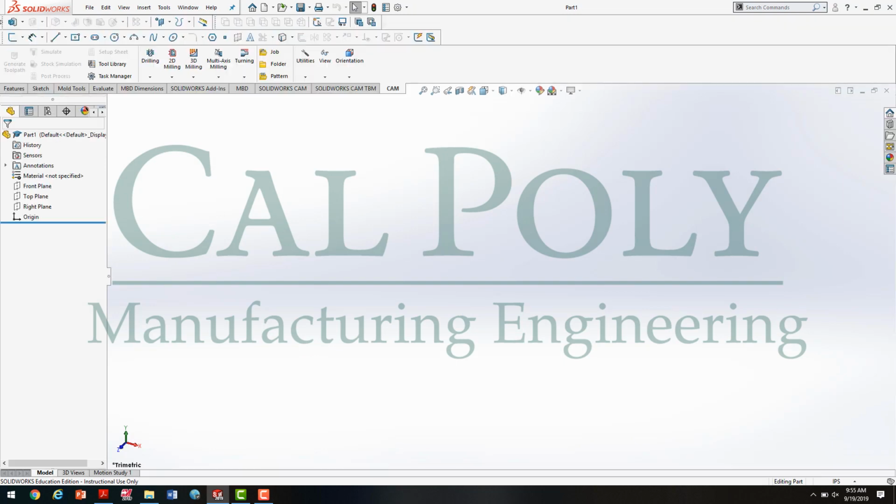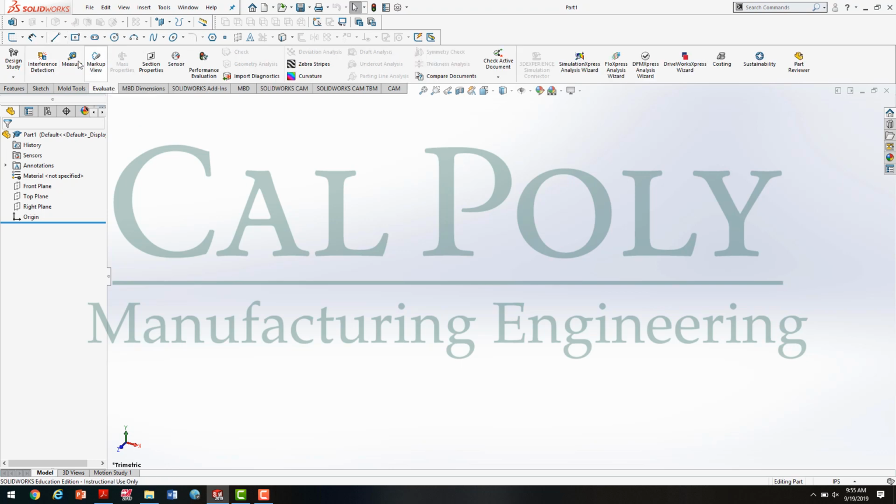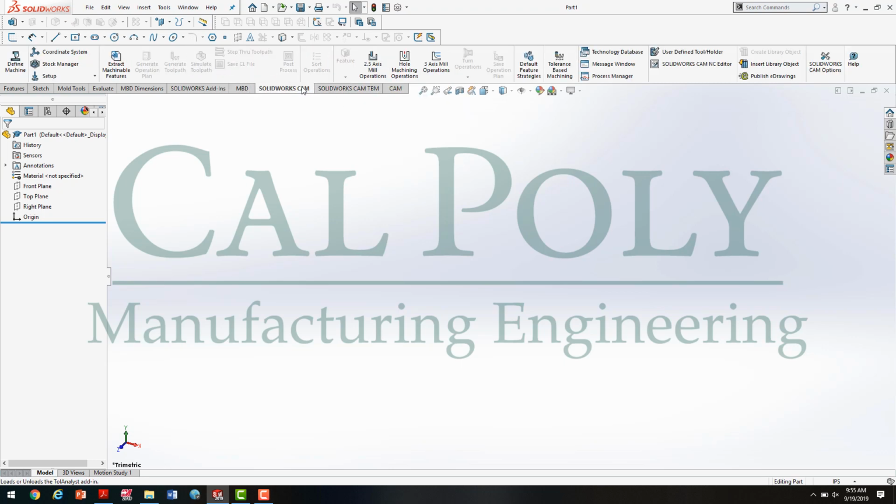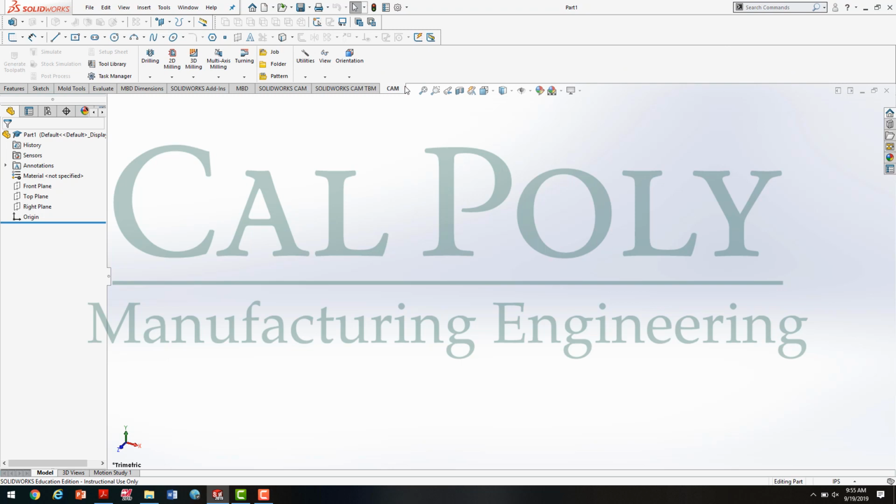Looking at the part environment, I have tabs. I have features, I have sketches, then I've got some advanced tools like mold tools. You may not have that shown right now, but it is available in your SOLIDWORKS. I have evaluate, which allows me to measure stuff and perform different measurement activities on my model. I have some other SOLIDWORKS add-ins, such as simulation and motion, which we'll get to in an advanced video later on in the quarter. I have SOLIDWORKS CAM, then also HSMWorks CAM. We're going to pretty much focus on just the features and sketches ribbon tabs.